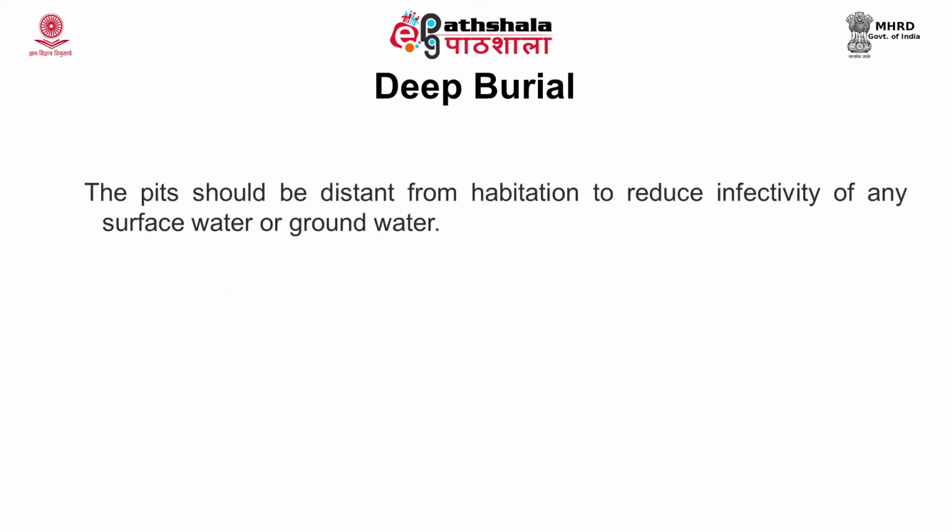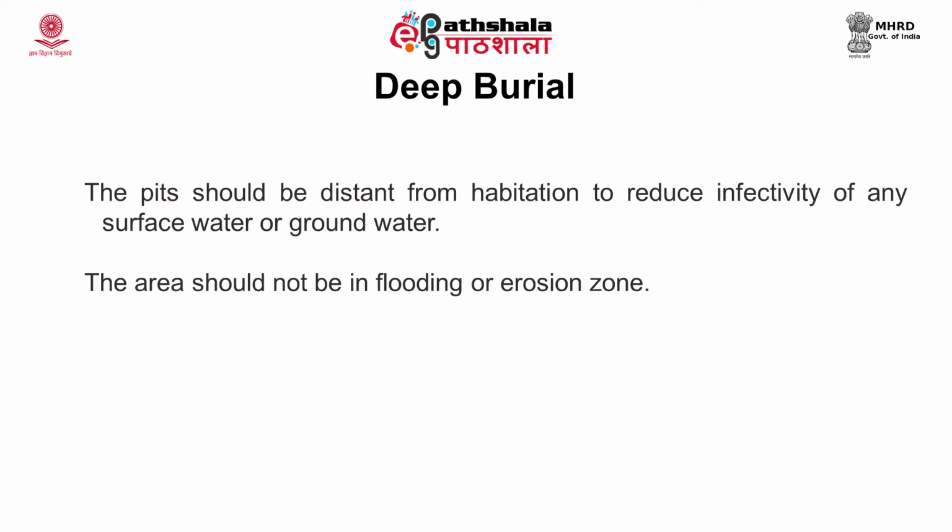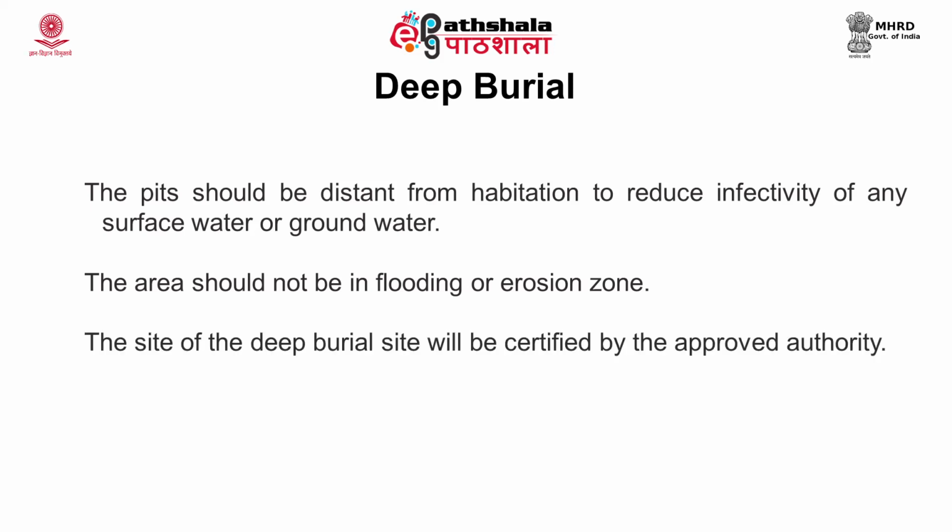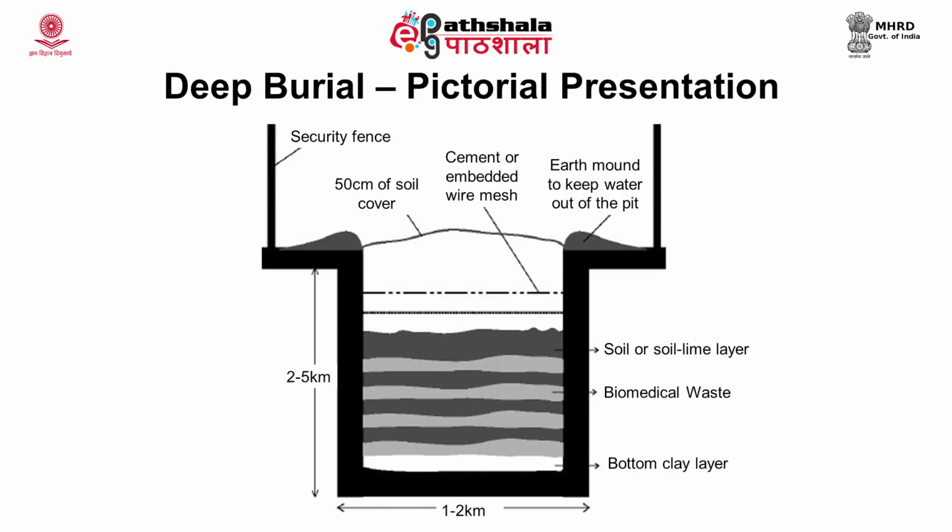The pits should be away from the habitation to reduce infectivity of any surface or groundwater. The area should not be in a flooding or erosional zone. The site of deep burial should always be certified by an approved authority. This figure shows a pictorial representation of a deep burial unit.